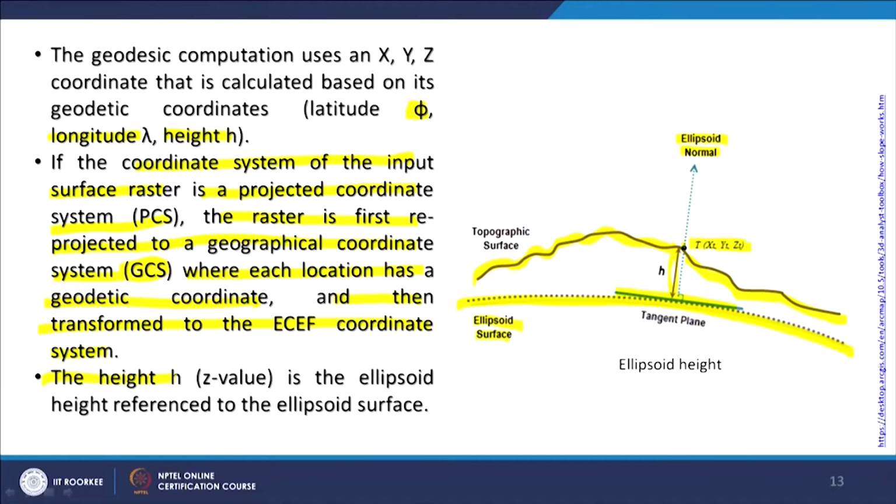As height is z, the z value is the ellipsoid height above this surface, whereas we say above mean sea level. So this reference becomes our ellipsoid, though that can also be adjusted to above mean sea level. But again that depends on the model based on our gravity surveys of the earth.